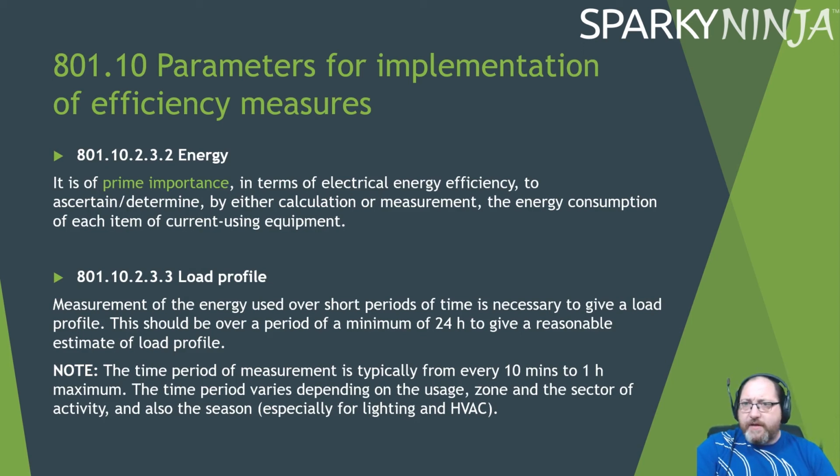801.10.2.3.2 energy. Okay, it's of prime importance in terms of electrical energy efficiency to ascertain or determine, by either calculation or measurement, the energy consumption of each item of current using equipment. Load profiling. Measurement of the energy used over a short period of time is necessary to give a load profile. This should be over a period of minimum 24 hours to give a reasonable estimate of load profile.